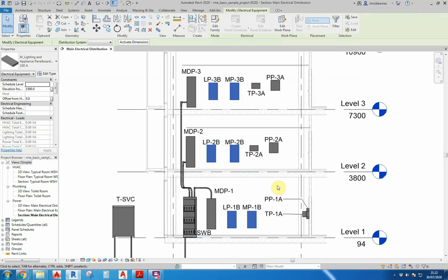Now, as an extra hint for selecting options, we have these commands down here. This particular one here, when toggled on and off, you can select linked drawings or Autodesk Revit models. When it is toggled off, you cannot select them when using the modify or move command.